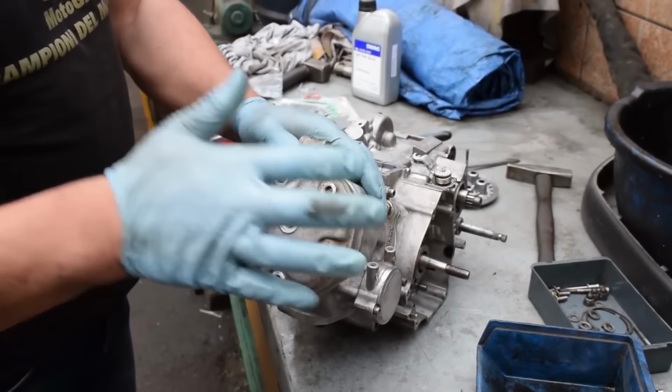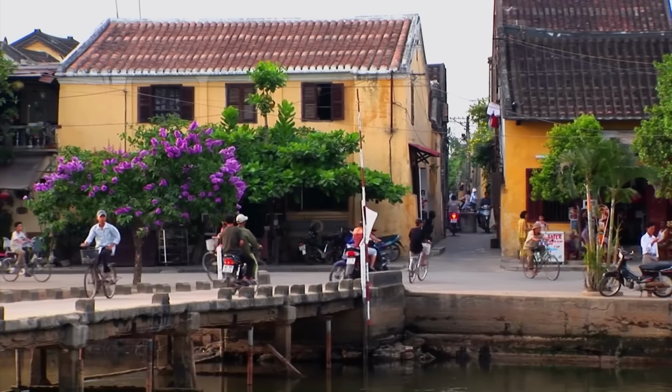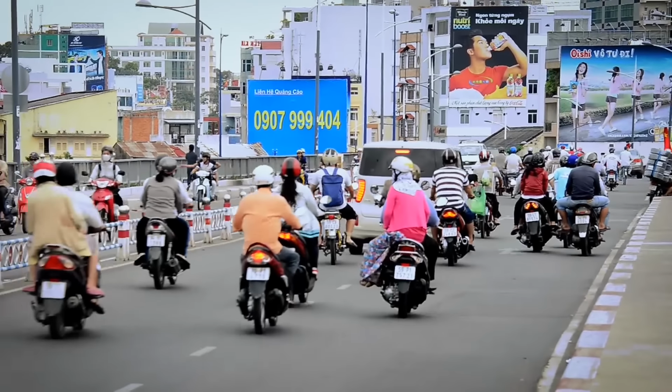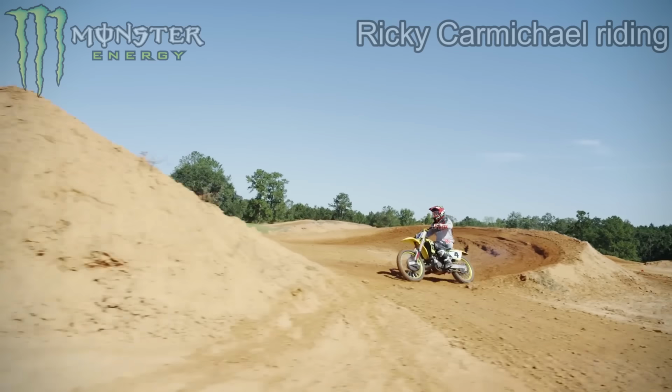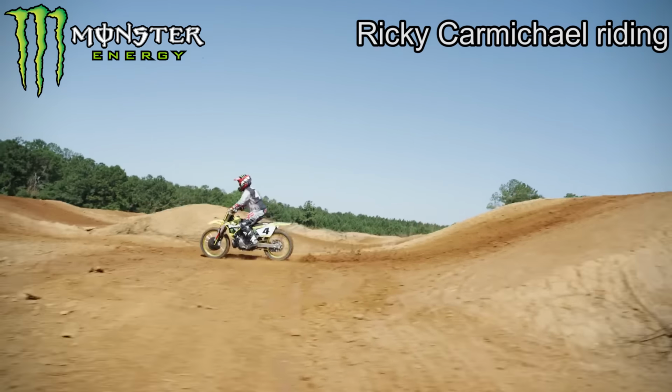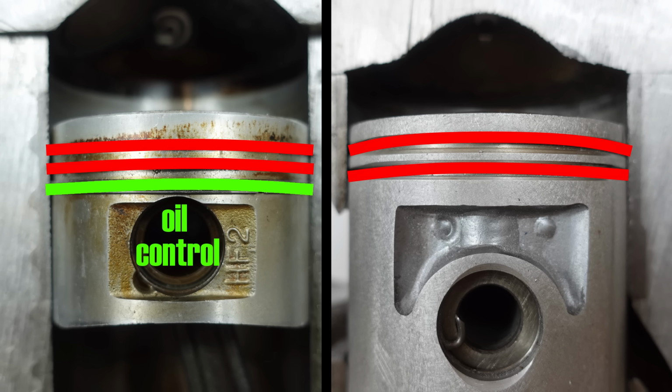The other problem with a total loss lubrication system is that burning oil is obviously very bad for emissions, which is the key reason why many legislations around the world have outlawed the manufacture of street-legal 2-stroke vehicles and only allow off-road and competition 2-stroke vehicles to be made and sold. The difference in lubrication systems between the two engines is also embodied and evident in the piston rings. The 4-stroke has 3 rings, whereas the 2-stroke has only 2. The third set of rings in a 4-stroke are oil control rings, and they prevent oil from getting into the combustion chamber. Oil control rings are obviously unnecessary in a 2-stroke because the oil gets into the combustion chamber anyway, with or without them.